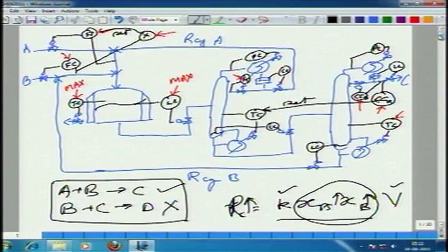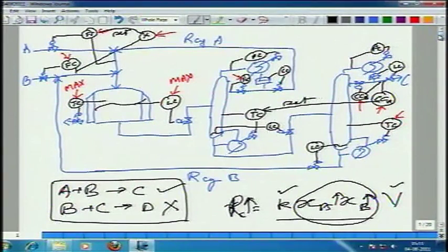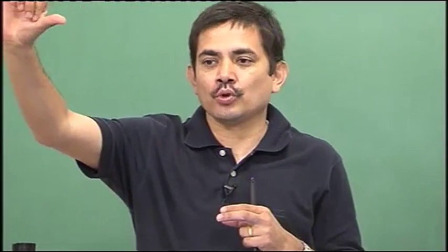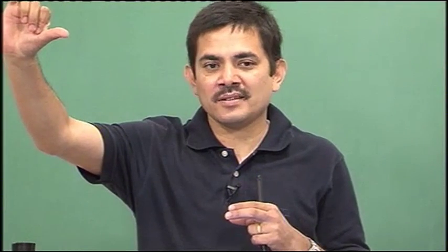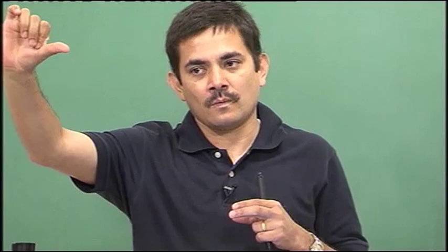So, if you have a side reaction, I get back to the same process. If I have no side reaction, reactor temperature should be max, maximum allowed. But if I have a side reaction, as I start jacking up the temperature, the side reaction rate grows faster than the main reaction rate. Therefore, I start producing more D per kg product C produced, or per kilomole product C produced. My selectivity or yield to desired product starts to go down. So, there is then a trade off.